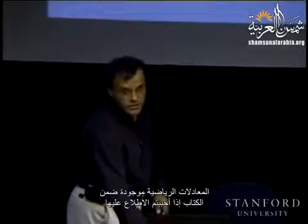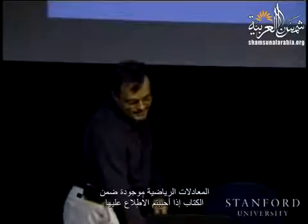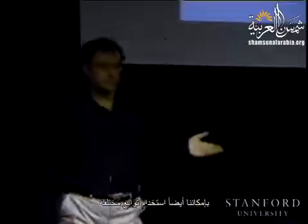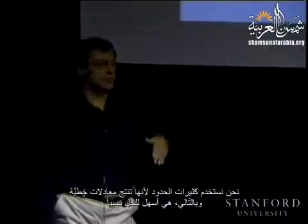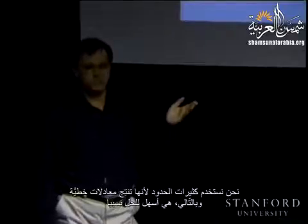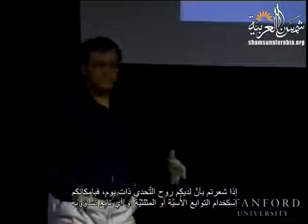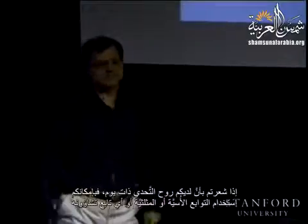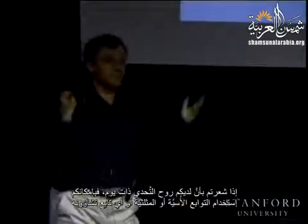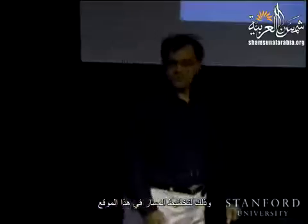The formulas are actually in the book if you're really curious to see what they look like. Now, another thing is we can use different functions. We're using polynomials because they result in a linear equation, so it's relatively simple to solve. If you feel particularly challenged that particular day, you can use exponential functions, trigonometric functions, whatever you want, to plan the trajectory in the space.